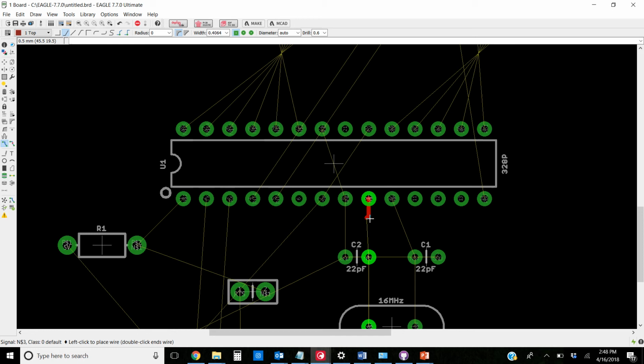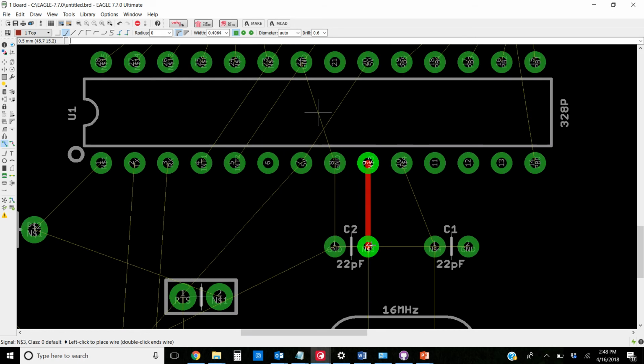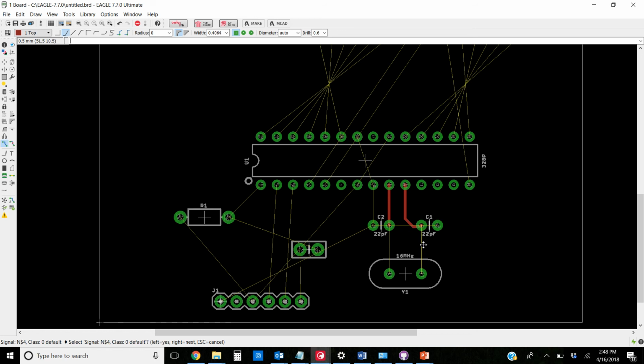I like this type, usually works well for me, and in this case we just want to make a straight line down, so I bring it over to this and just click, and boom, we have now routed that line. And for the other one, I'm going to just stay with that line, bring it over there, and we're just going to stay on the top layer.